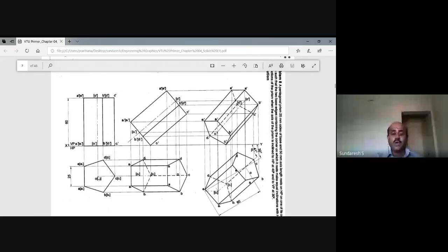Let us take O as the point of the axis on the face, whereas O1 is the point of the axis on the base. So O1 represents the axis. In a similar way, you can project it to the front view by drawing vertical projectors down to the XY line.